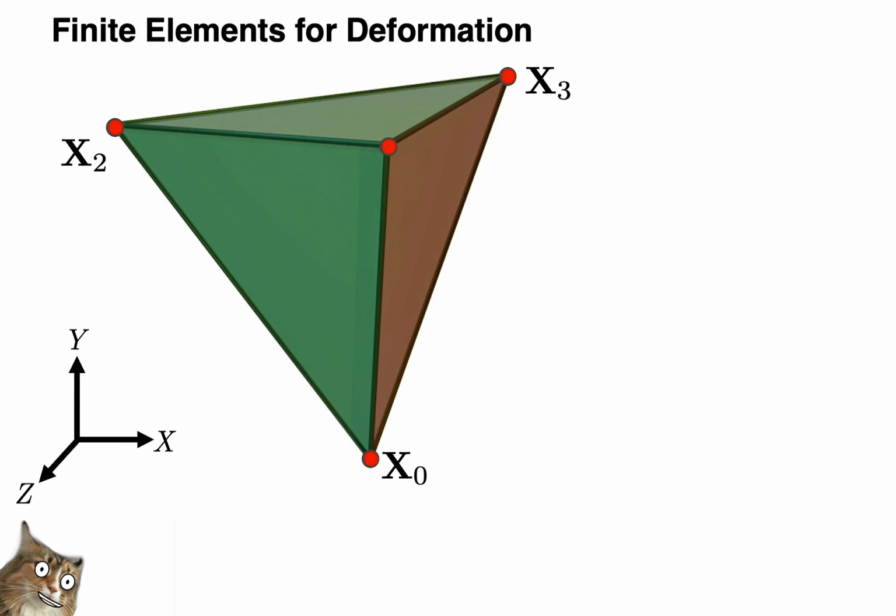Let's go back to where we started, our undeformed tetrahedron. We embedded this tetrahedron in 3D space via its per-vertex coordinates, the capital X's. We are going to give this particular 3D space a name. We'll call it the reference, or undeformed space. In this space, our tetrahedron takes on its undeformed shape. The undeformed shape is analogous to the rest length of a spring. It's the shape a chunk of material takes on in the absence of all applied forces.